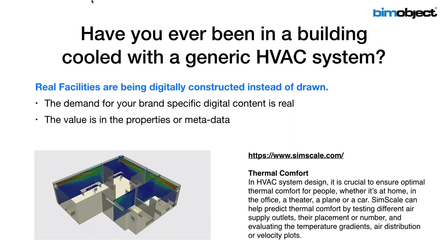So in this case, SimScale, they're actually doing a virtual design and simulation where they're looking at airflows in a given facility, and it even gets so sophisticated where they can actually place this room that you see in the image here in a certain geographic latitude, longitude, and do a sun study, and based on the current glazing in those curtain walls and a current HVAC system and current airflows with specific air outlet devices, specific duct sizing, specific coefficient of drag within that duct, specific CFMs coming out of an air handler.